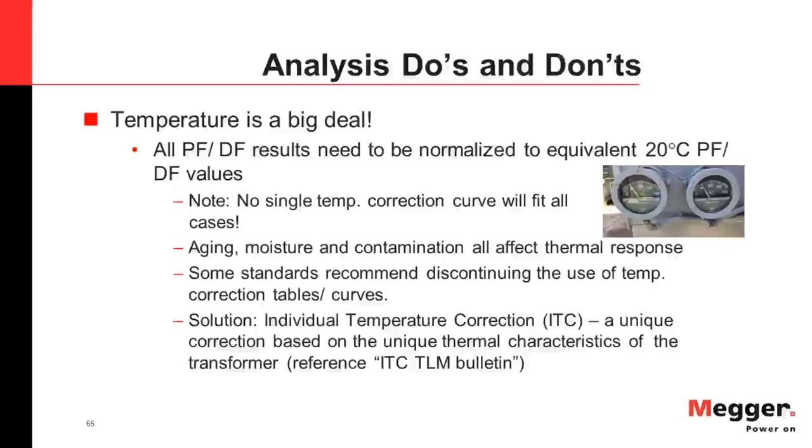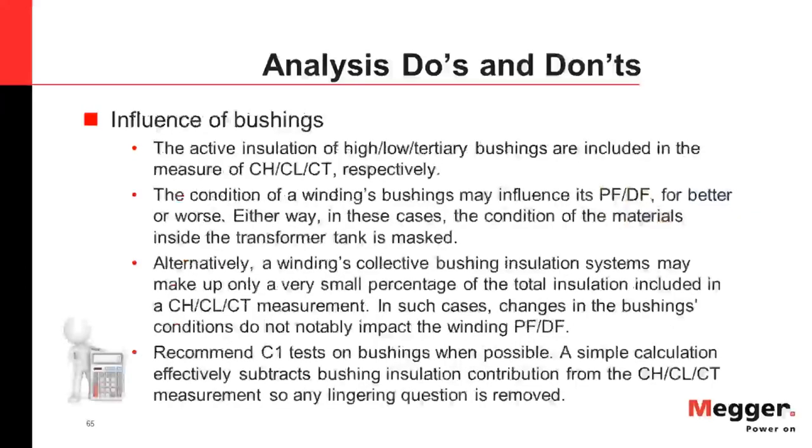With regard to the influence of bushings, keep in mind that the active insulation of, for example, your high voltage bushings is included in the measure of CH. And the condition of the bushings may influence the CH power factor in this case for better or worse. Either way, in these cases, the condition of the materials inside the transformer tank is masked, because you don't want it looking better than it is or worse than it is.